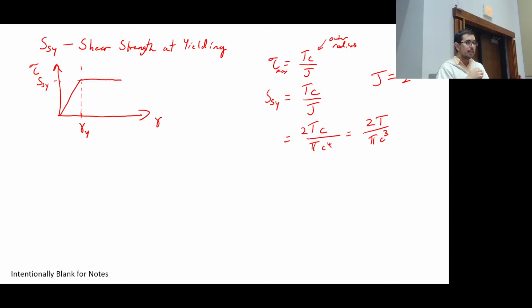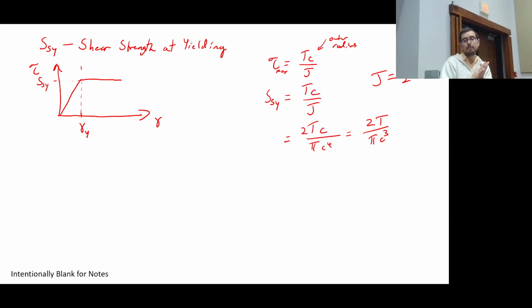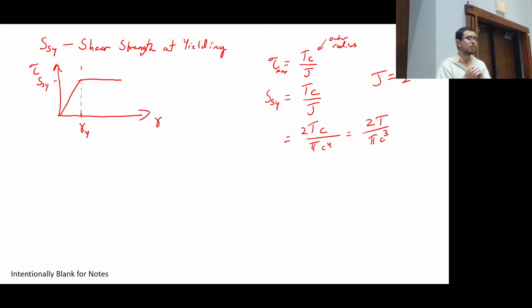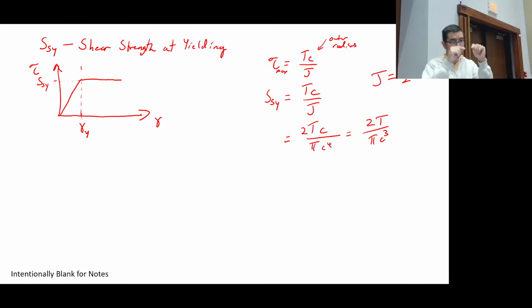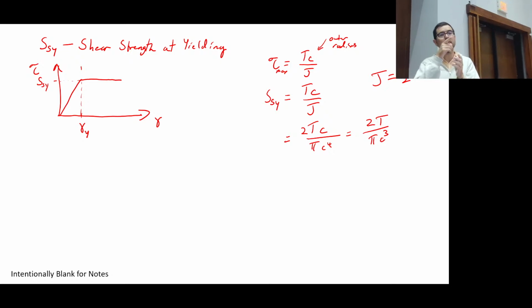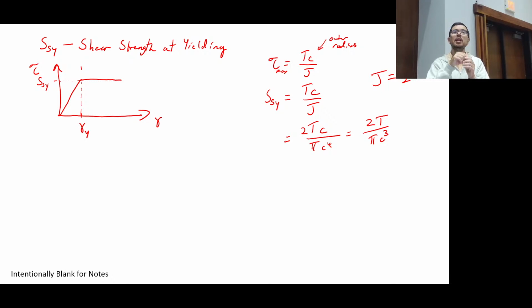And then they also have stress concentrations because of the threads in the screws, which have kind of sharp curvature to them, and so that can increase the effective stress, especially under fatigue-based systems.